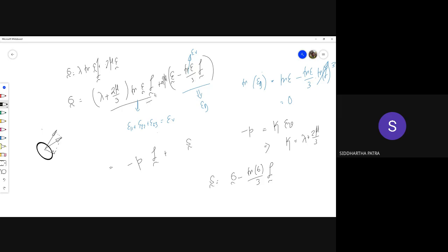Which basically means if you take this tensor and epsilon d and do a matrix inner product, see, this part is all scalar, right? So the only matrix over here is the identity tensor. So if you do an inner product over here, basically this means that you take the individual terms of the identity matrix and the corresponding terms of epsilon d, multiply them and add them up.